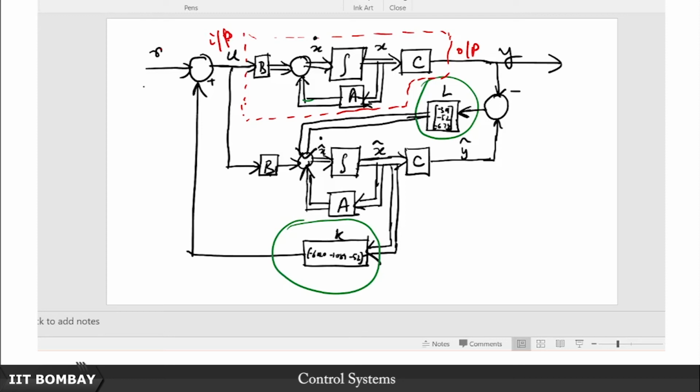Now of course you might say anywhere you like, so maybe in a third order system I want one pole to be complex and two poles to be real. Of course you cannot place that with real coefficients, because you have to respect those things. If you want a characteristic polynomial to have real coefficients, then if you choose a pole at 1 plus 2j, you have to have another pole at 1 minus 2j. So when I say I can place the poles anywhere I like, there are some restrictions, but that is very commonsensical.